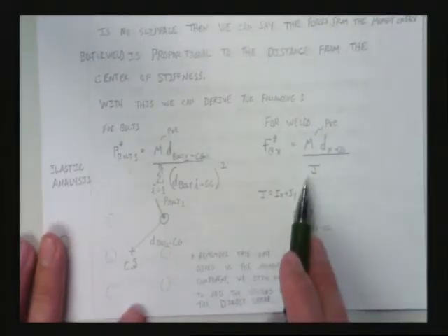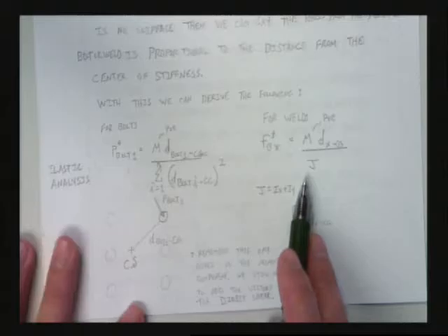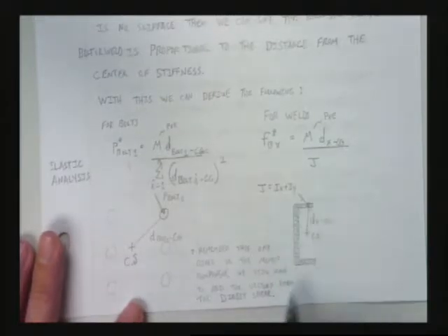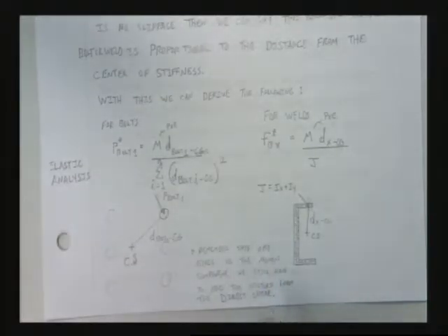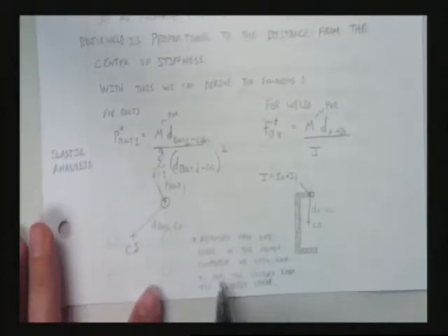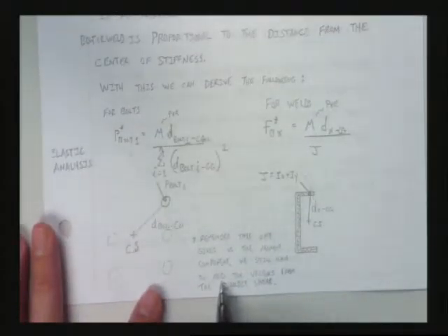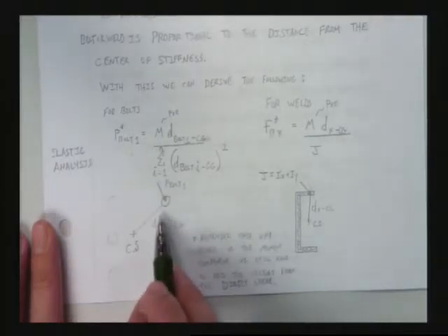And it's really similar to MC over J, okay? Because that's what you actually use for a weld. You actually found a J, torsional coefficient for the welds. And remember, this just gives us the moment component. Doesn't give us the shear component. Then we have to keep track of all the vectors, and we have to add all these up.